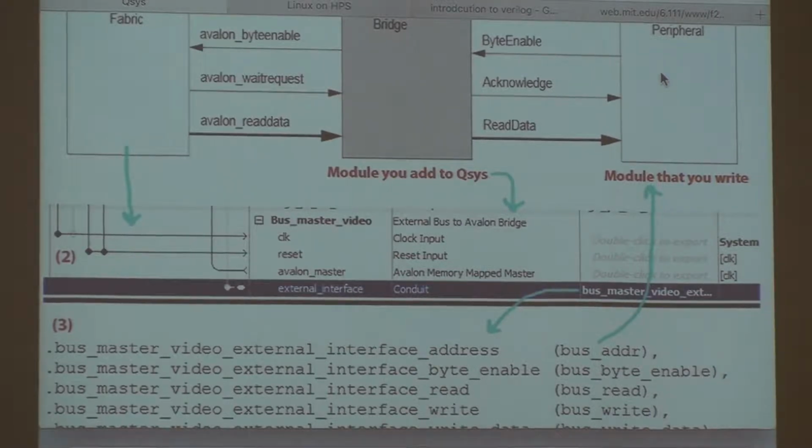Because in lab 2 the pixels that you write are going to be determined by the dynamics of the system that you were simulating in Verilog. You're going to be dynamically simulating a spring mass system, and the positions of the masses will be plotted as trajectories on the VGA by a bus master. Any questions?